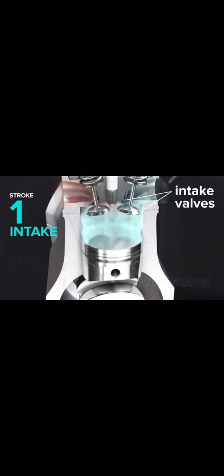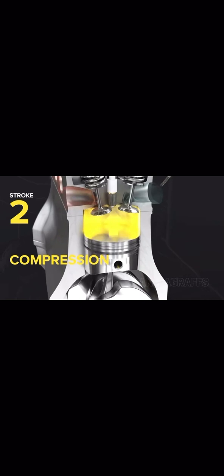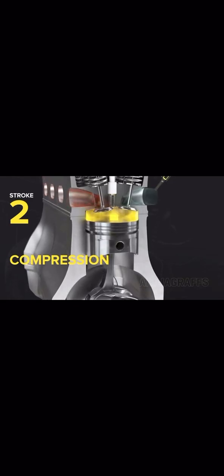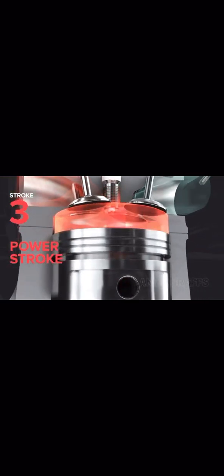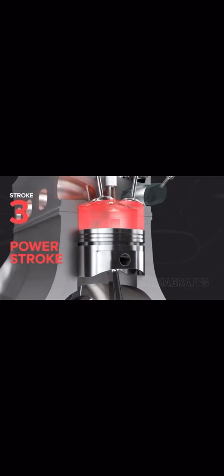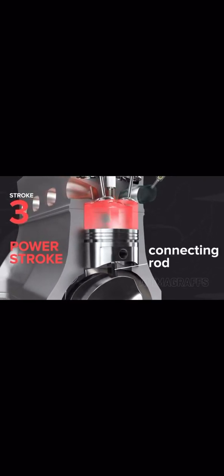open. Next, compression. With all valves closed, the piston comes back up, compressing the fuel and air mixture for more powerful combustion. Then, the power stroke. An electrical spark ignites the compressed fuel and air mixture, and the resulting combustion forces the piston to the bottom of the cylinder again. A connecting rod transfers this power to the crankshaft.